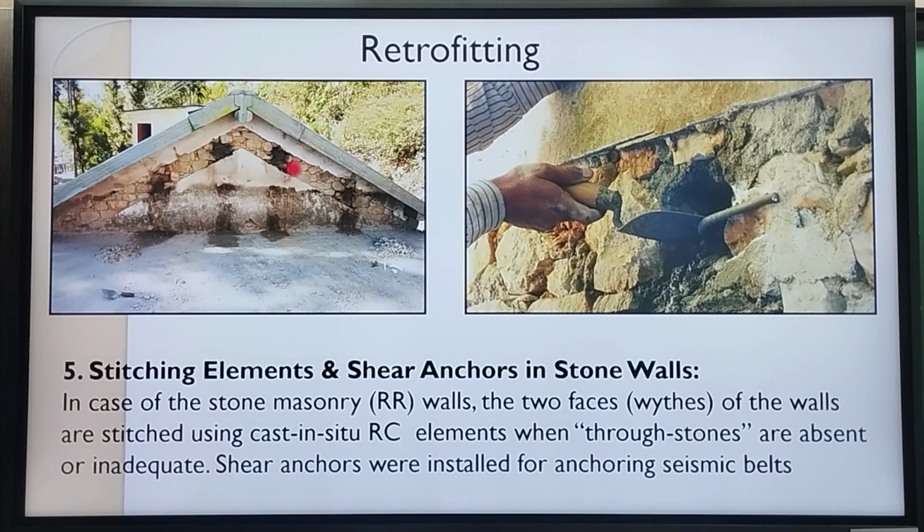So here again, you can see these are the shear connectors, and that's the part of the shear connector. You can see the legs sticking out, and the hole is then filled up with concrete and is cured. And then the weld mesh is tied with the binding wires properly with the shear connector sticking out. Alright.